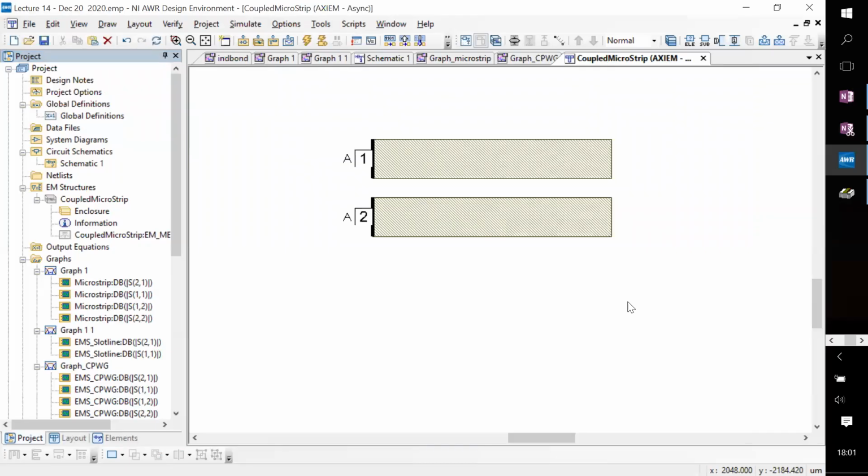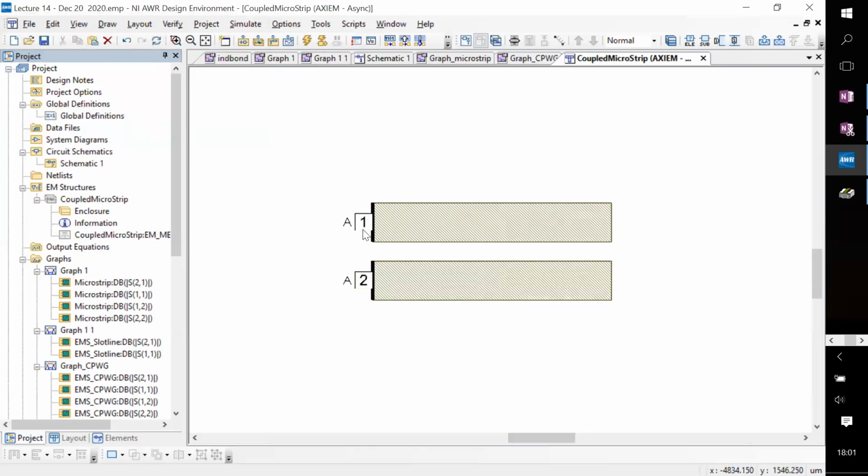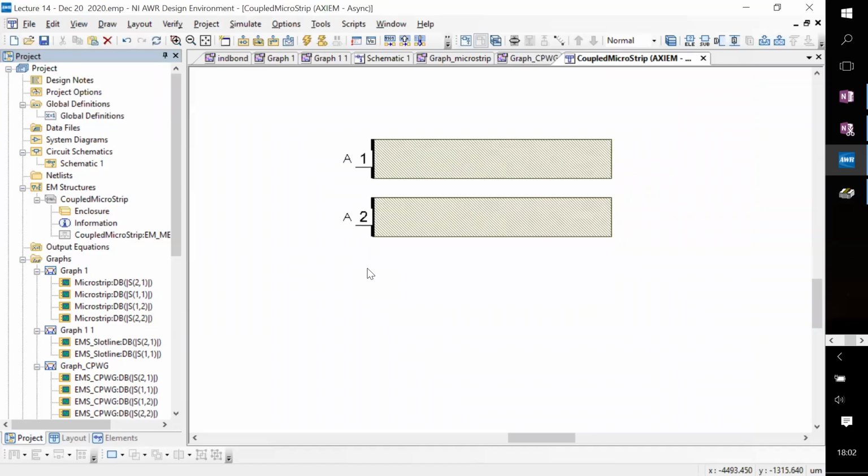Okay, so now these kinds of coupled microstrip lines or strip lines usually have separate ports for each of the structures, even though what exactly they mean now is slightly confusing. So we will come to that. What I mean by that is that these ports are 50 ohms by definition, and how we measure the properties in this normal mode frame is what we're going to see.